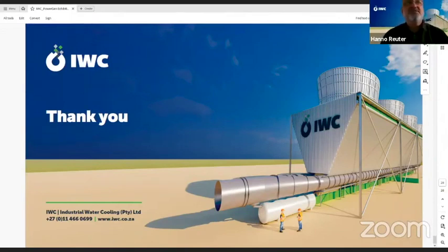Now, how this works, Matthew, thanks for the question, is the steam turbine power output is determined by the pressure difference across the steam turbine. And the cooling system determines what the outlet pressure is of the steam turbine, and ultimately how much power you can extract from the steam. If you use a wet cooling system, you can achieve a much lower pressure at the steam turbine outlet than you can achieve with a dry cooled system. As a result, you get more power output in a wet cooled system than a dry cooled system.